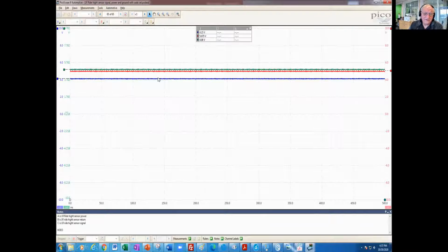When you have a ground circuit that's at high voltage, that's a really good indicator that you've lost your ground. So we see the sensor sitting at 5 volts, power sitting high, the signal sitting high as well. There's a lot of stuff here indicating that we've got a ground problem with this particular sensor.